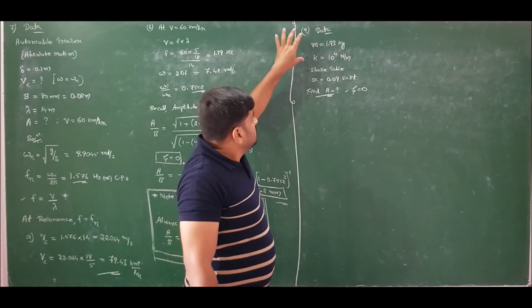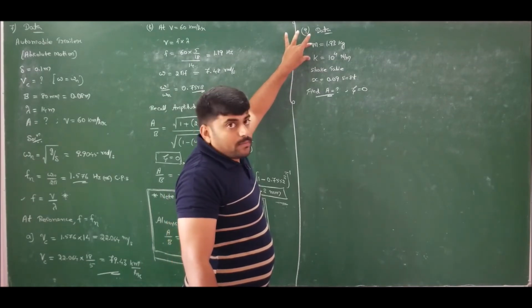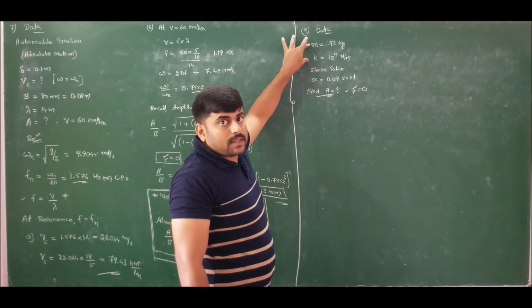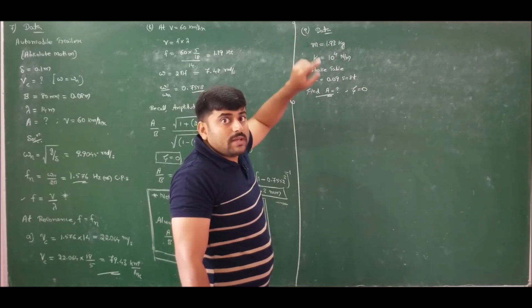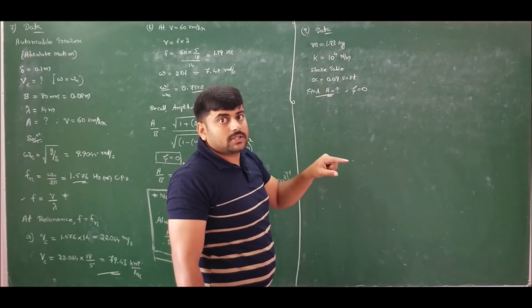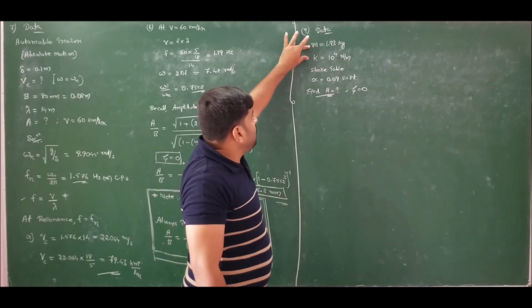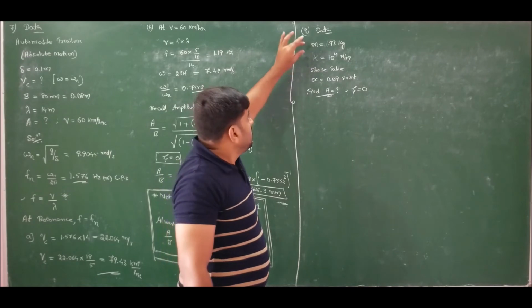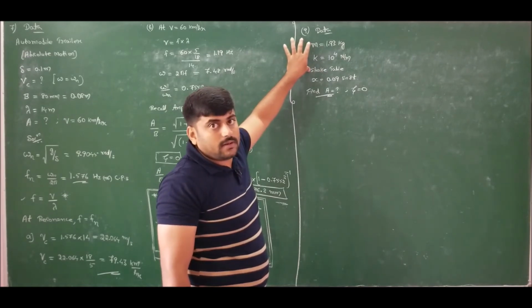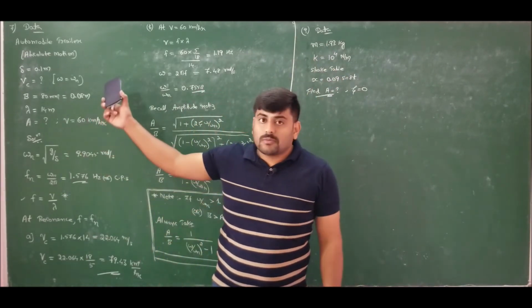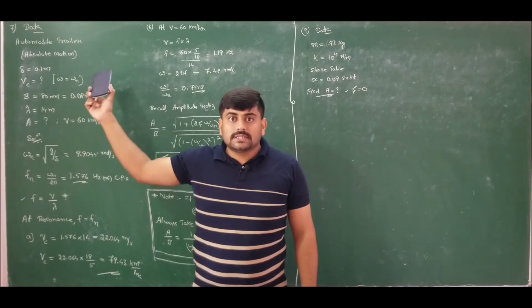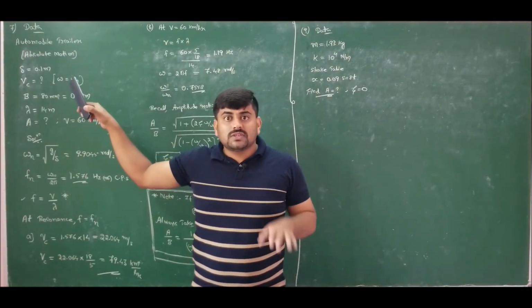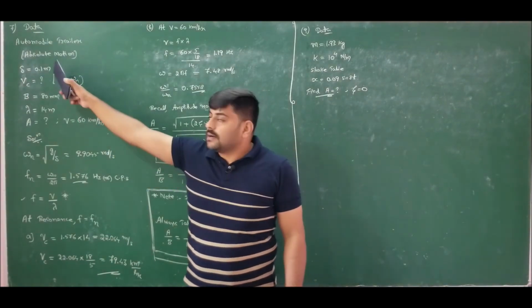Then the vibration amplitude measured by this spring mass system is measured with reference to a vibrating object which is already vibrating. So whatever amplitude is indicated by this will be relative in nature. Unlike the case of an automobile. Automobile is vibrating but it is moving on a road which is fixed. Therefore, it is absolute motion.